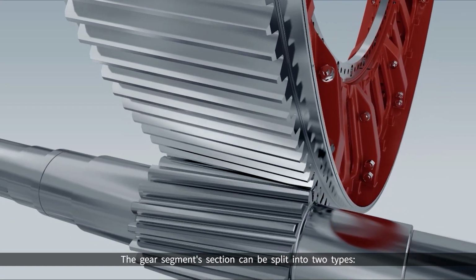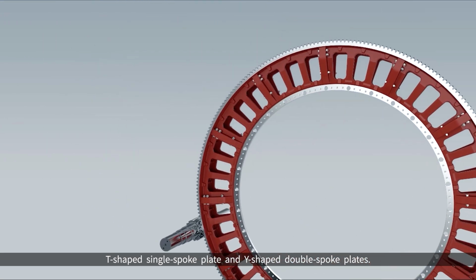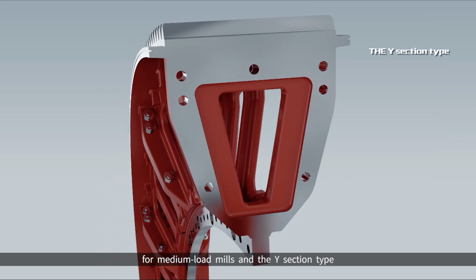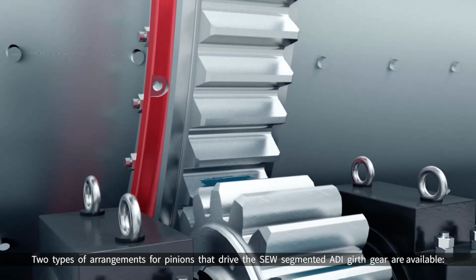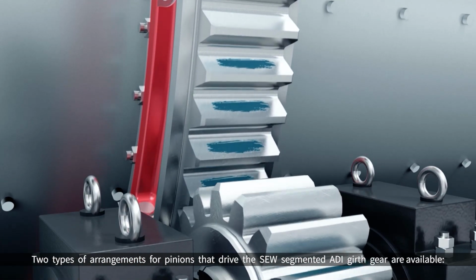The gear segments section can be split into two types: T-shaped single spoke plate and Y-shaped double spoke plates. The T-section type of gear segment is ideal for medium load mills, and the Y-section type has higher structural stability for heavy-duty mills. Two types of arrangements for pinions that drive the SEW segmented ADI girth gear are available.